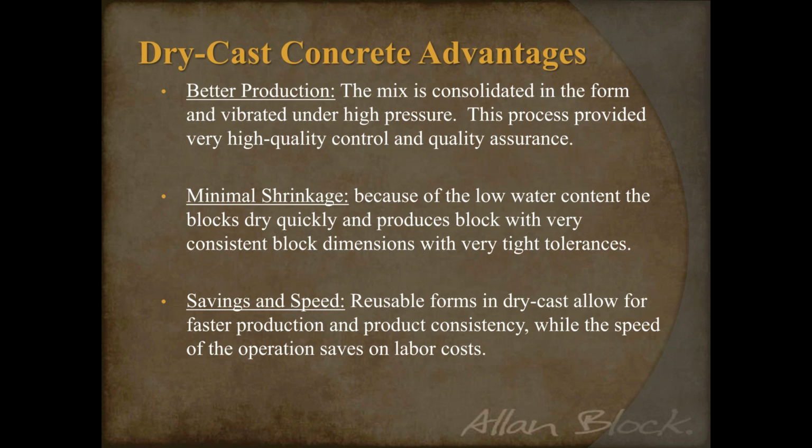Because of the low water content of the block, the blocks dry quickly, and they produce blocks that are very consistent in dimensional tolerances, which is very important. We don't want block to come out of the machine and then start to have temperature cracking and so forth for shearing during its drying process.